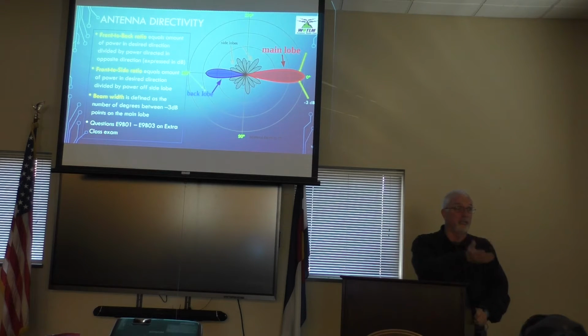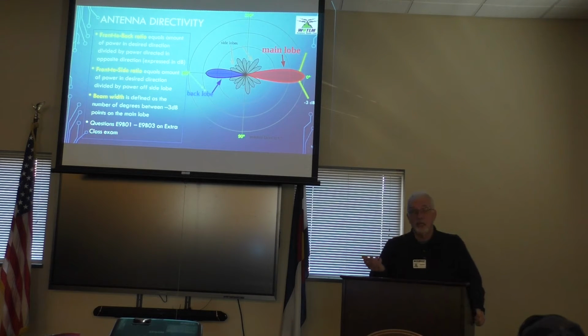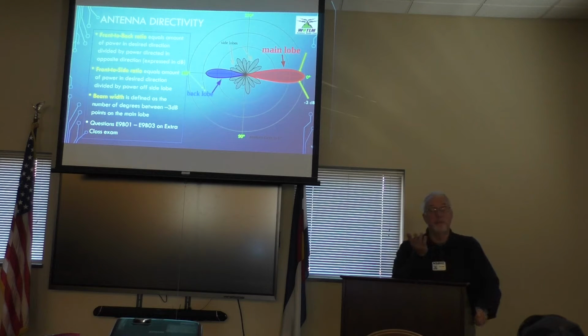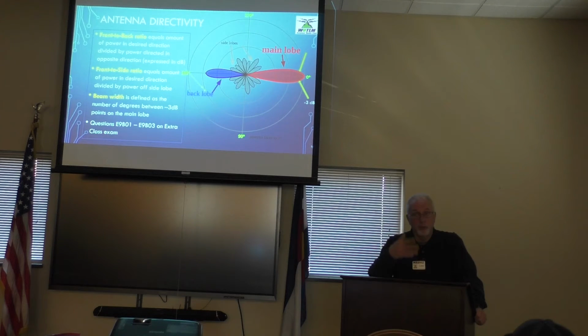to where it's doing better probably because it's up in closer to free space than it is, and it's a much more efficient antenna than that little dot. In many cases, back to that original question of, does an antenna need to be resonant at the frequency it's being used at? Well, that antenna is nowhere close to resonant at the ham bands. But well, one of the jokes is, with the right antenna tuner, you can load up a bicycle frame or a light bulb, and people have done experiments.